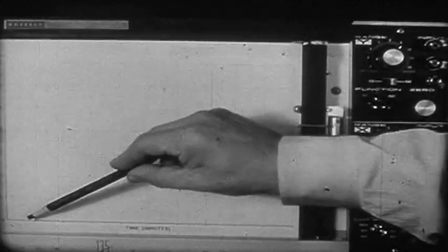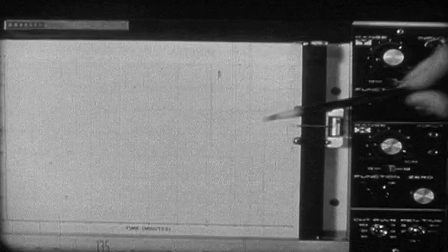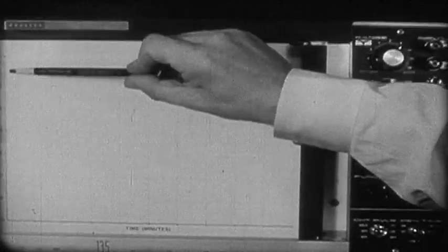It is a so-called XY recorder. The horizontal, or X, motion will be so used as to indicate the lapse of time as cooling proceeds. The vertical, or Y, motion is connected to the voltage lead from the tin wire. It is calibrated in millivolts.